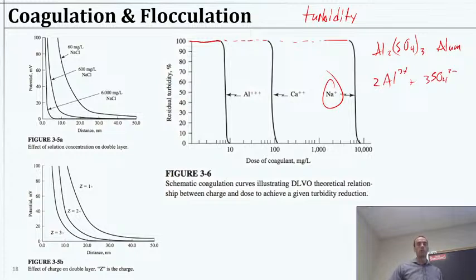And that charge is great because then we're really compressing that electrical double layer quite effectively, and we're not adding much of it. It also turns out we can cause aluminum to come back out of solution, to precipitate it, very easily. Oftentimes we'll precipitate it in a manner that also is creating particles for stuff to stick to. So it's kind of a win-win to use aluminum here.